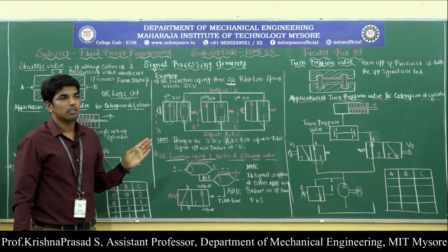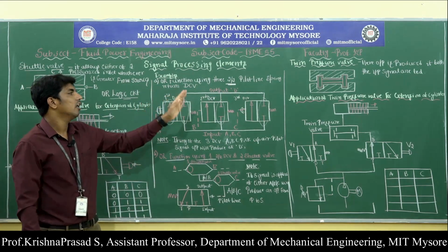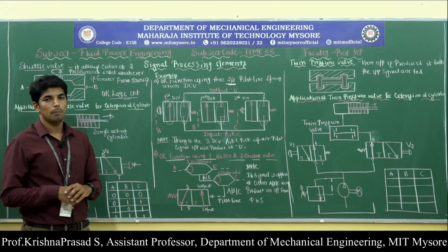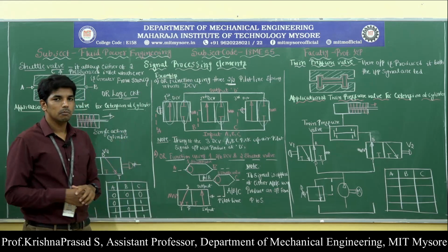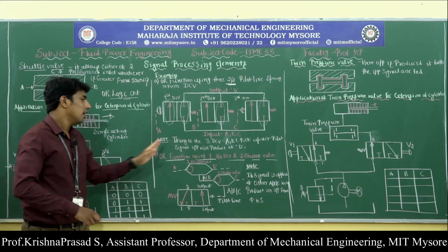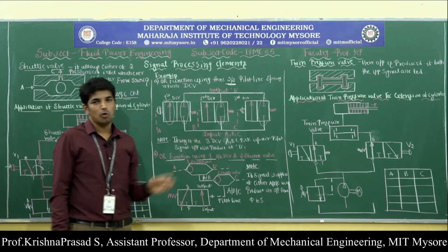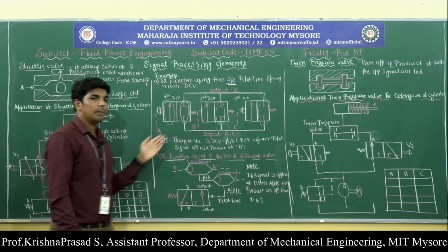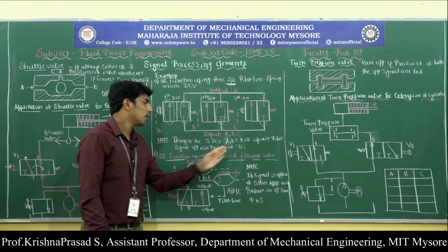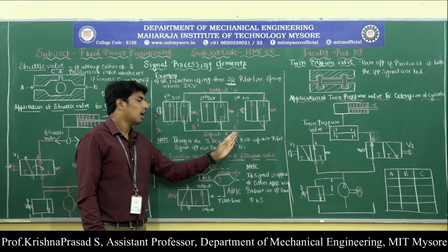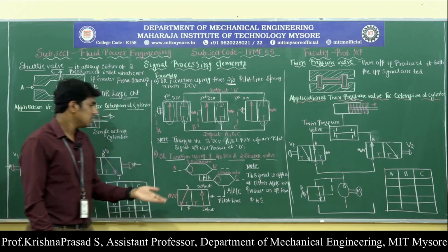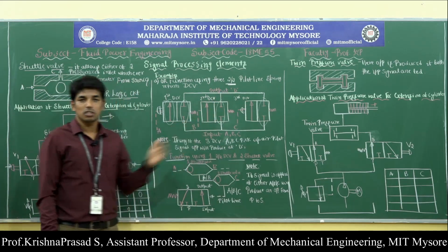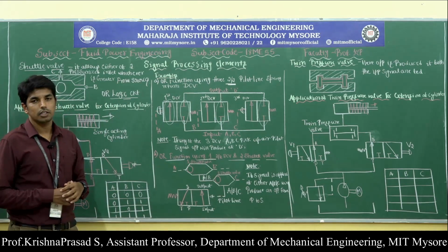So this is regarding the OR function using three 2x2 pilot-line spring return direction control valves. Observe here, very important: if any one of the three direction control valves, that means V1, V2 and V3, picks up the air signal from either A or B or C, or all three signals, then output will be produced at point D. So this is the first example of the OR function.